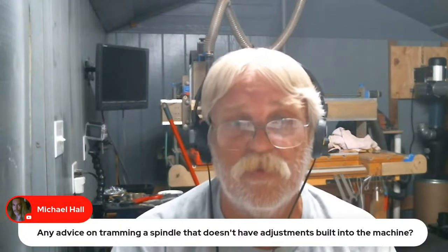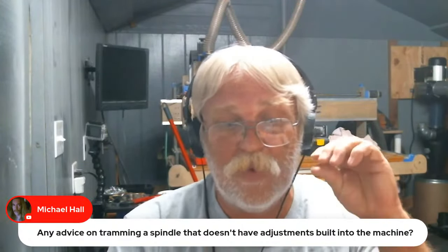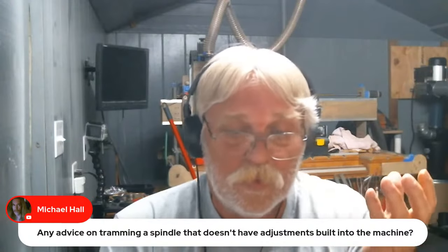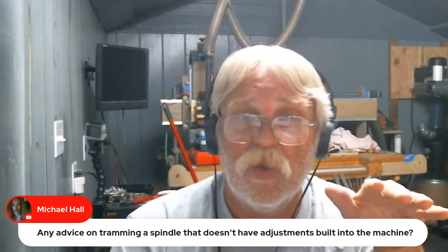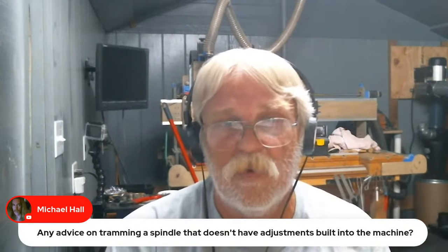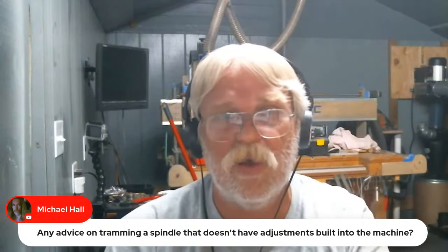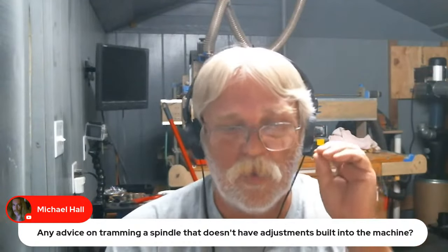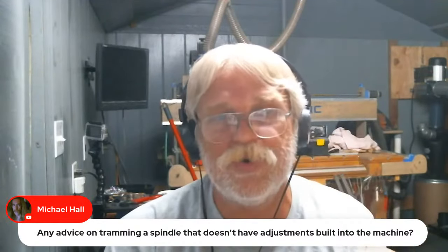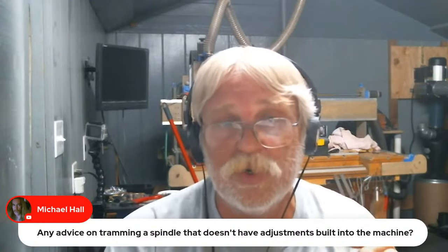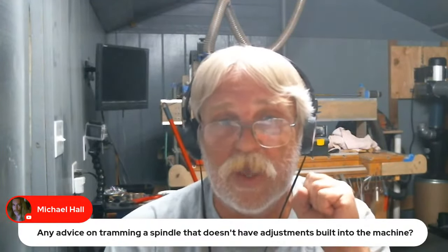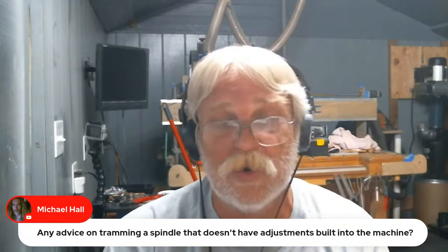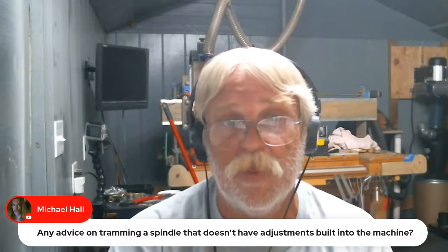Wood is going to move. So if you are 0.02 of an inch out of 0, you're fine. Number one, you can't see 0.02 of an inch. Number two, any moisture changes, to include the moisture that's in the glue when you're gluing 2 pieces together, are going to make that wood swell more than that 0.02 of an inch anyway.